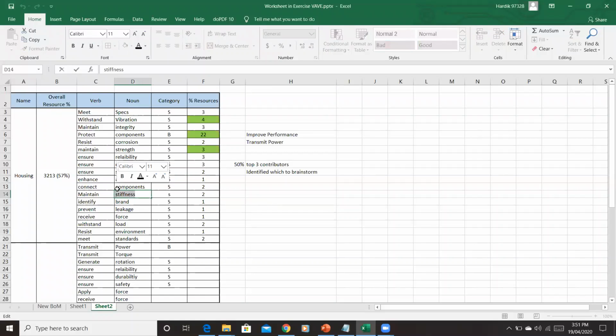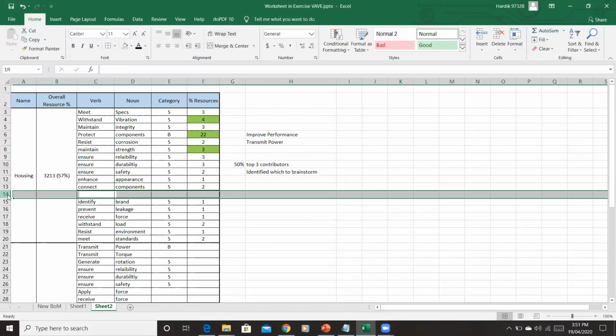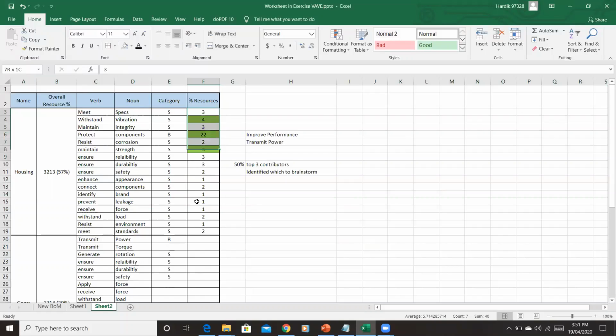Okay. So then toughness, should I write toughness or what? That much individually we don't need to mention too much. Okay, then I'll remove that. Even stiffness also is not good, but mostly for spring we go for stiffness. Basically load by deflection. Deformation can happen in housing also, because of the load and vibration, but stiffness is mostly applicable for this spring.